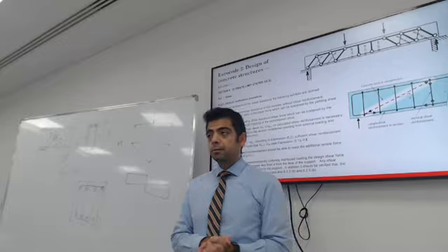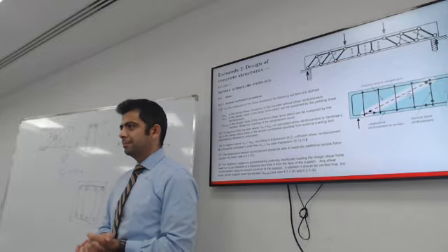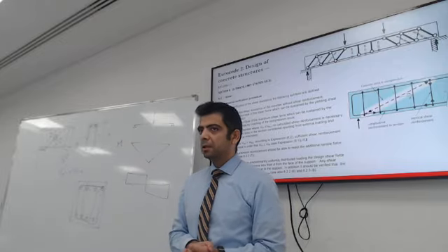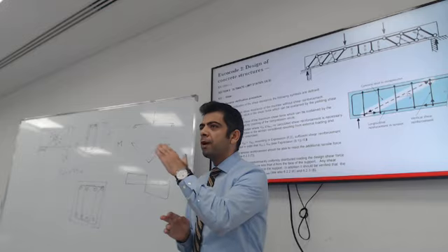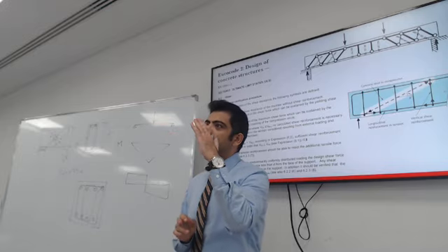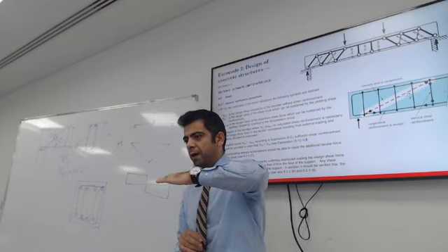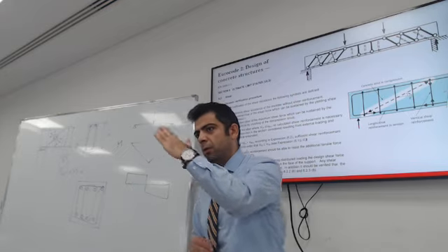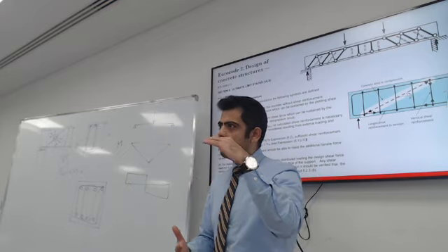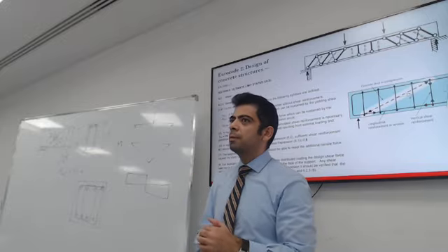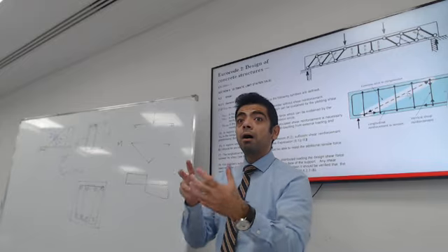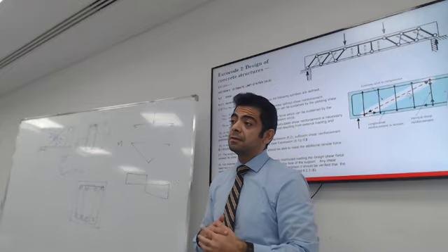It will fail. What's that? Above 45 degrees, this means the load is very close to the support. I will show you what that means. Less than 45 degrees, the crack is going to be very long and it will get mixed in with flexure. It's not going to be a stable structure to resist that crack.